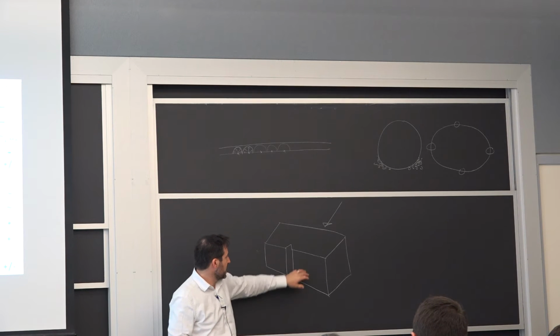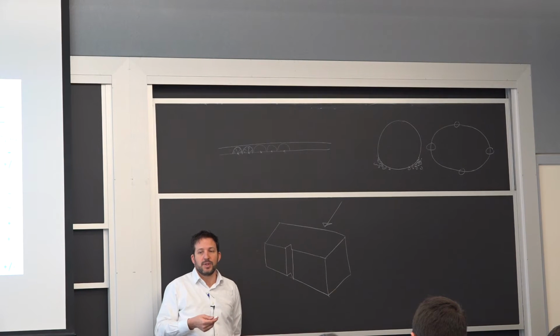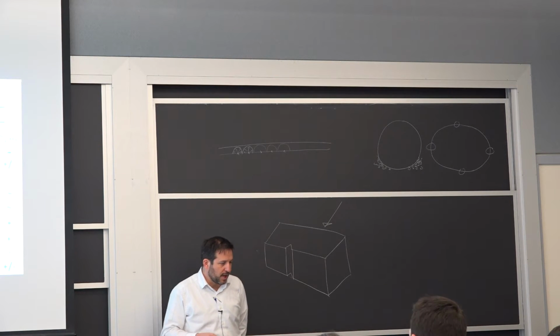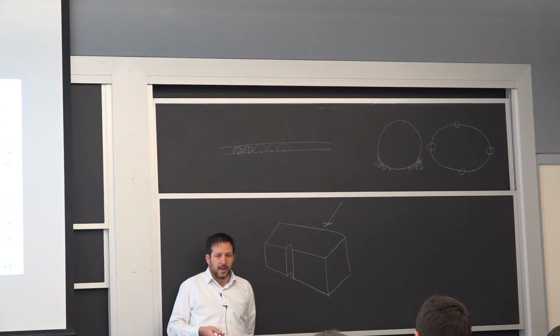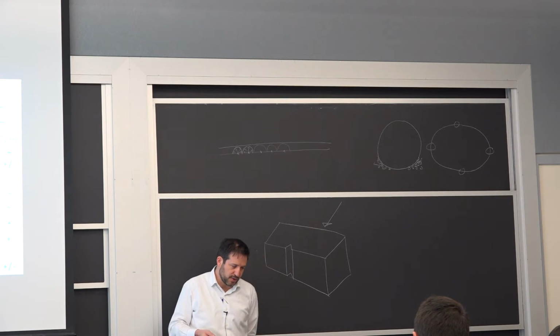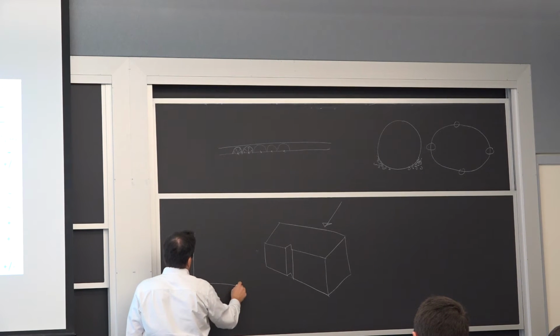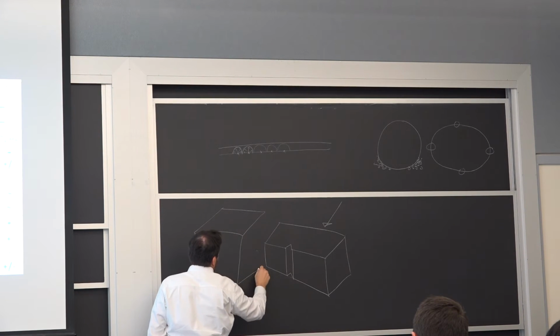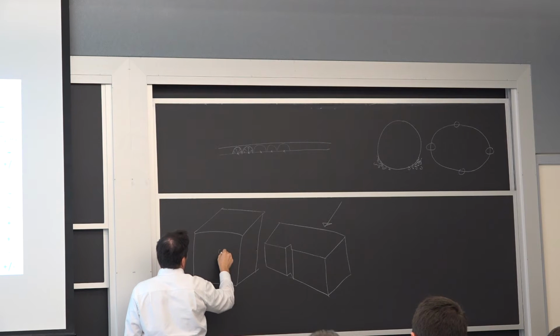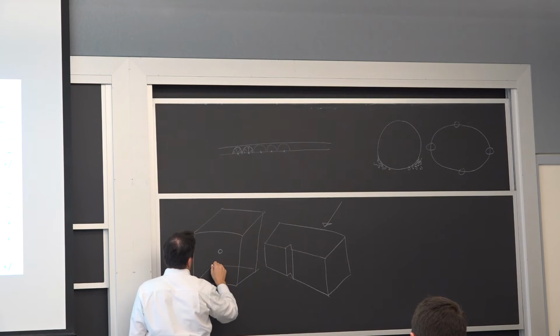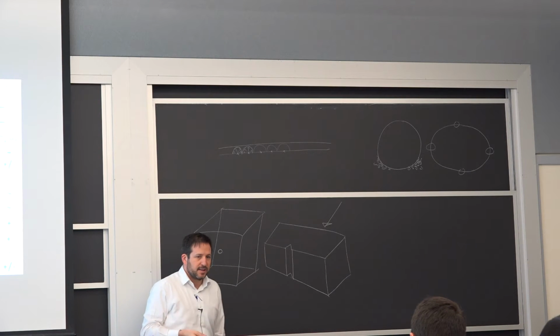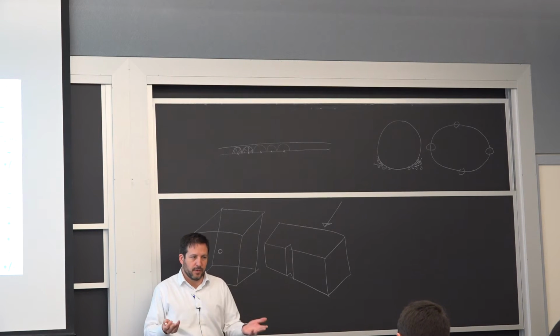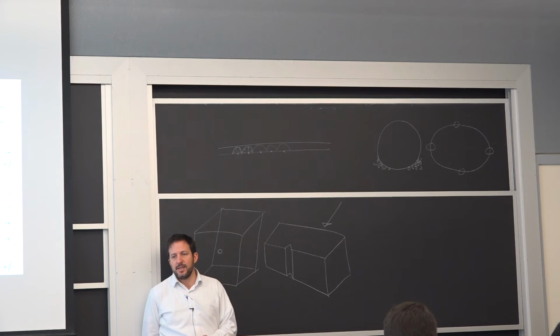It happens when you take your sample and cool it off just before the test, to determine at which temperature upon impact you're going to have a brittle behavior. There are a lot of reasons why it's specific to steel. Maybe the only one that you'll remember is that steel, despite all its advantages, is body-centered cubic. So when we look at it at the atomic scale, we have the cube and we have one atom in the middle of it. That leaves us with much fewer slip systems for deformation of that structure than if we have an FCC system, so a face-centered cubic like copper, aluminum.